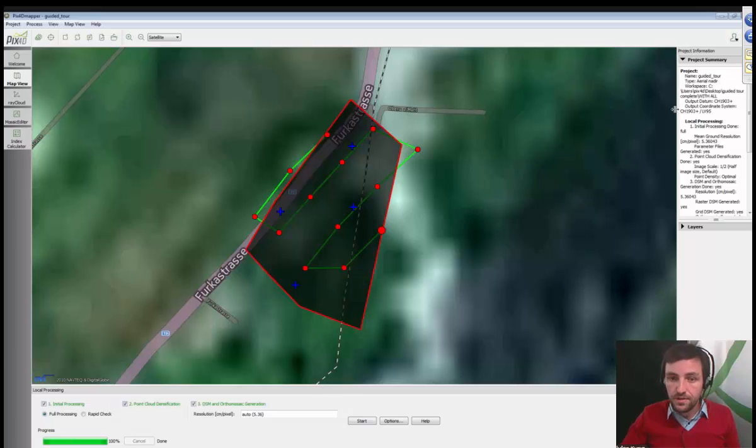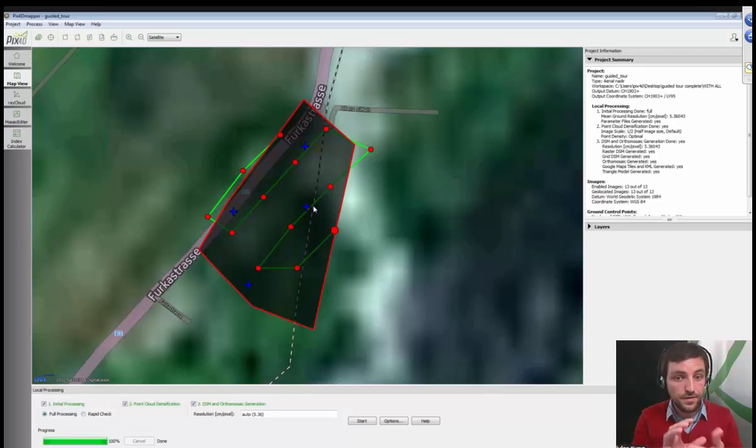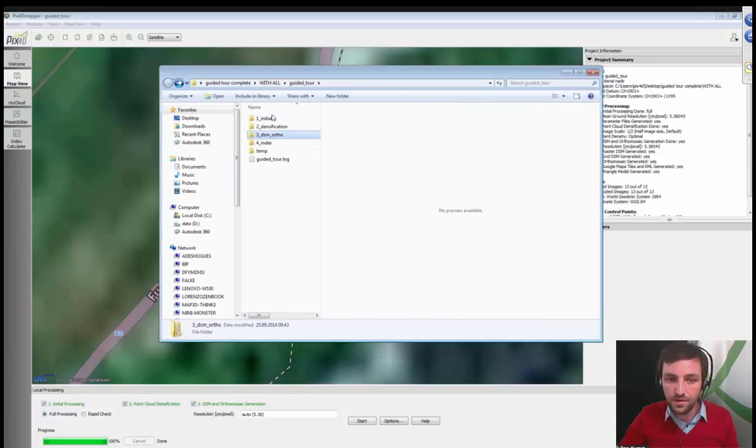When you created the project, as I mentioned just before, there is a directory that you specified where most of the files are going to be generated. So you don't have to click on Save anything, the files will be generated in that directory. When you are in the map view, you will see on the right a mention of that directory where the project has been processed. There is also a very useful icon on the top in the menu bar, called Open Result Folder. If you click on it, it will automatically open a Windows File Explorer at the right location.